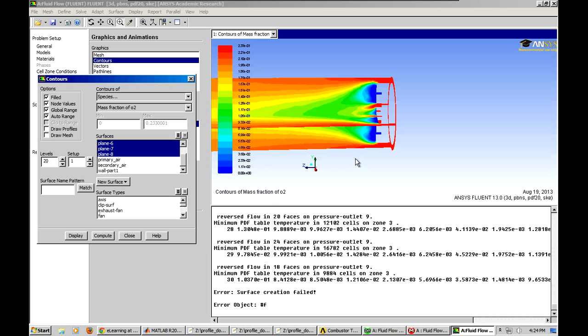And for those of you that watched my other combustion tutorial, which I recently took down, and this is replacing that, you'll notice the big difference between these contours versus what we had before, where before I had a lean mixture. I had not enough fuel in the combustion. I'm sorry, no, it was rich. Forgive me. It was rich, and I had too much fuel for the amount of air. I went back and corrected those numbers now in this tutorial. And this is what you should see. This is with 5.5% of methane in the combustion chamber.